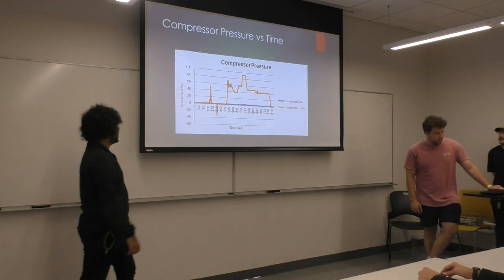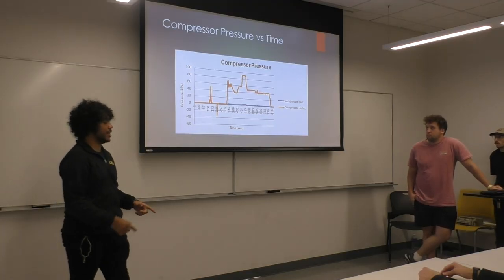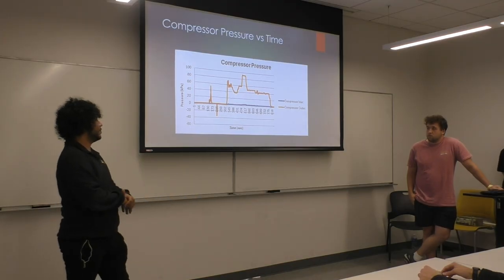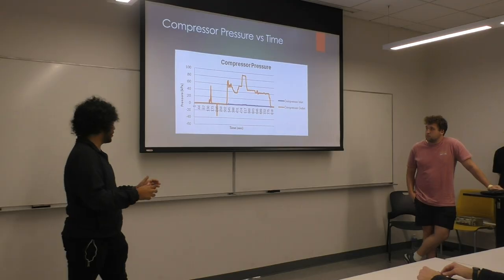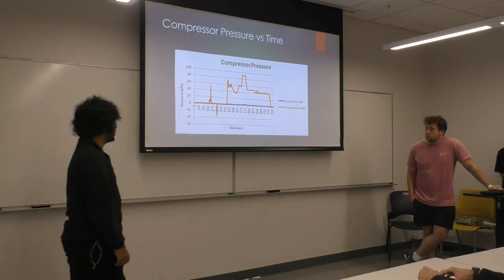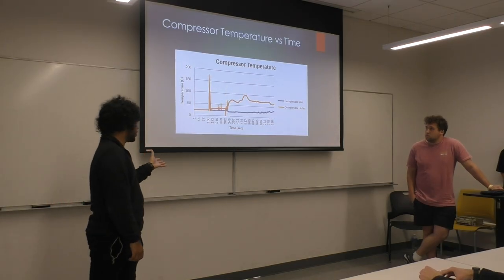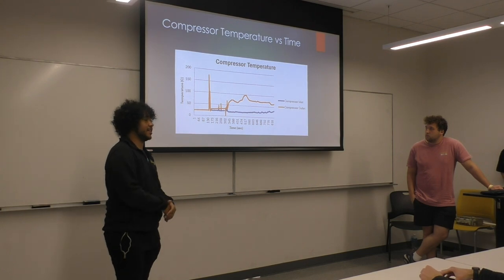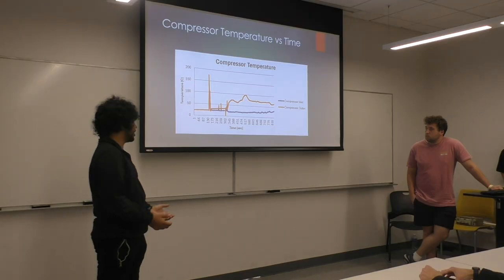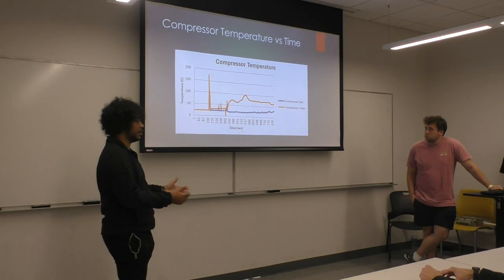As you can see, there's a huge negative spike in pressure. That correlated with a spike in the fuel flow. So it's probably some like fuel dump that didn't burn properly and caused back pressure that messed with the sensors. You can go to the next one. You can see that also with the temperature, there was a huge temperature spike, and that's going to be a kind of consistent thing across these. They're just going to have random jumps in temperature and pressure in either the positive or negative direction, mostly at the same point that the fuel flow peaked, so it's probably all a related issue.